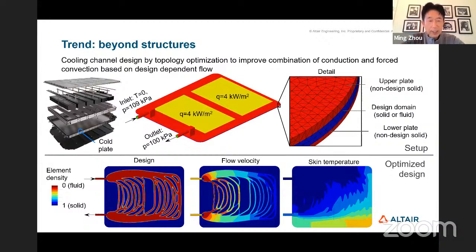So additive manufacturing is still relevant for sure, but the application will be pretty narrow, on more specific high-value problems. For example, if you do injection molding or casting molds, then designing and making conformal cooling channels in a very complex way with additive manufacturing should be highly valuable.